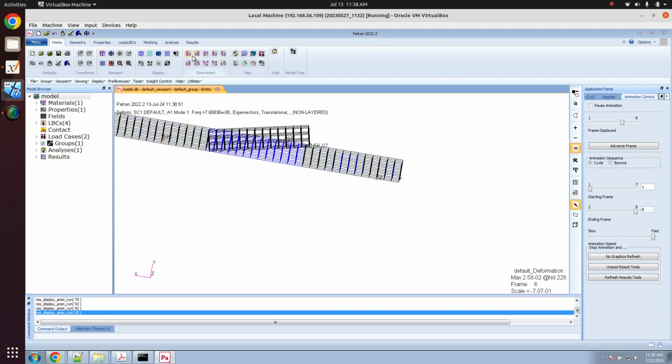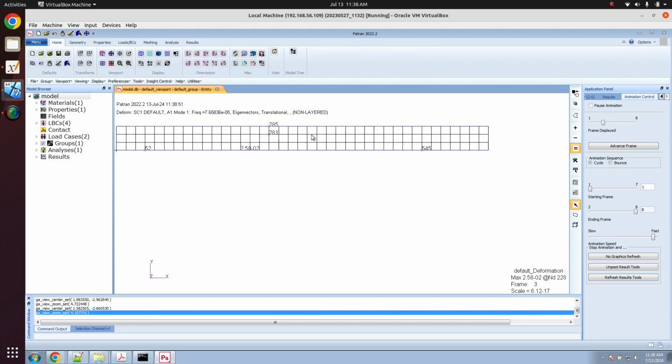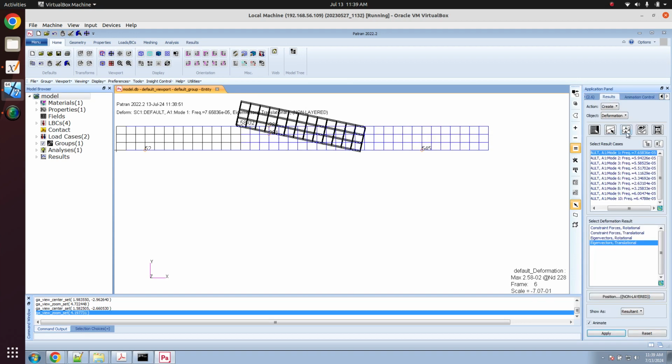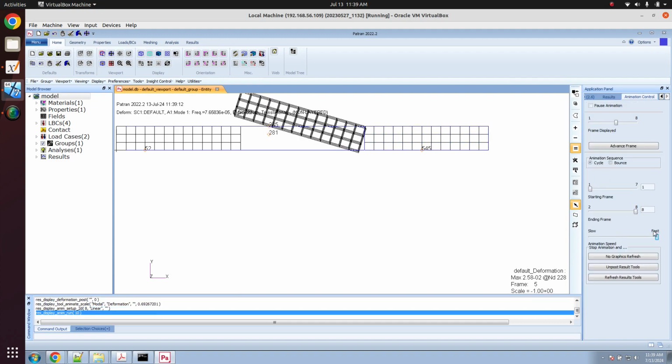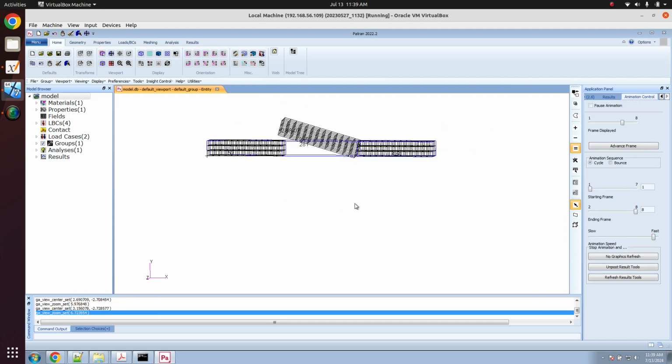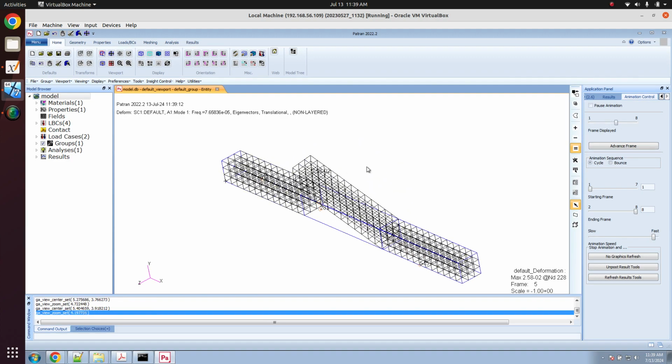And so here is the issue. This center region of the mesh is not attached to the rest of the model. This mesh does not have enough supports for equilibrium, so this mesh is unstable. Here, let me do this. Let me go ahead and redo this again. So here, I think this would give you a better idea of what's going on.